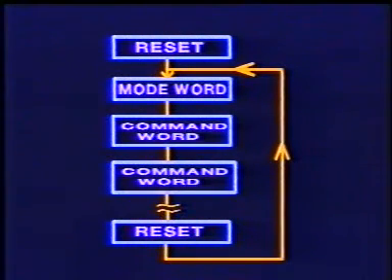After reset, the first write operation in this control register is treated as mode word, and the subsequent write operations will be treated as command word. That is, the command word can be changed at any time during the operation. However, to change the mode word, resetting of the device is needed. Resetting can be done using the reset pin or through the command word itself.